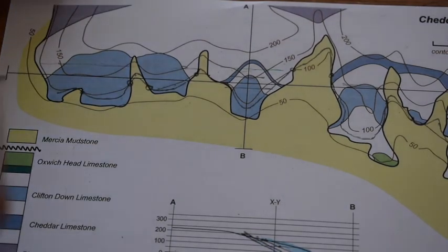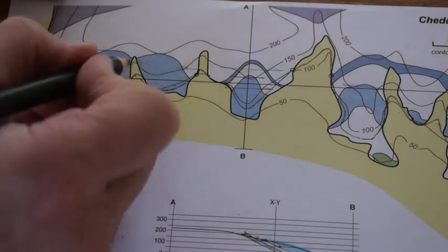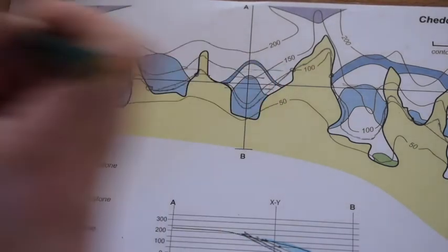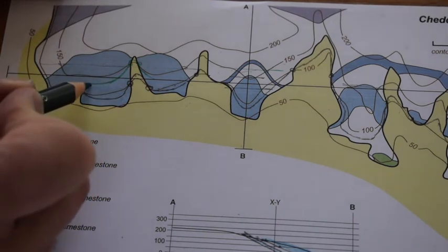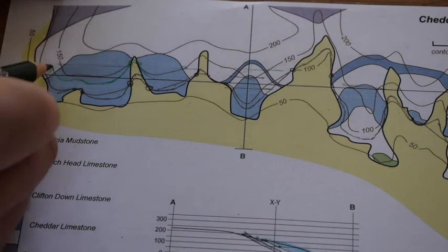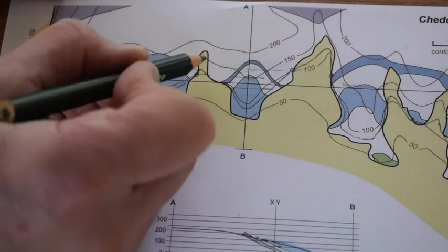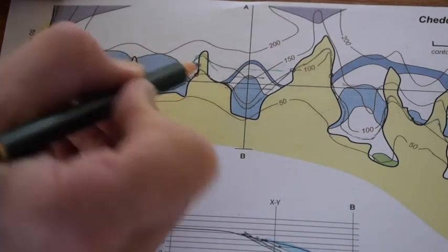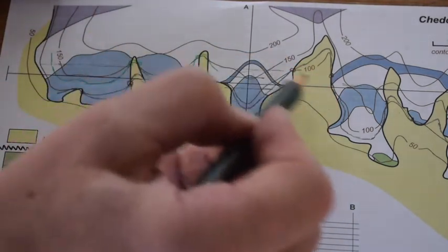We can do the same for the 150 structure contour. A couple of picks here and here. I'll just do it in green so we can pick it out. It's going to come in, whoop around, stay on this side of the 150 topo contour like this, presumably. Let's just add a little wiggle to honour that shape, and out somewhere like that and around. And as we come around here, it's going to have to intersect those 2 points and come out like that. So that's the structure contour, and we can keep going and going and going.